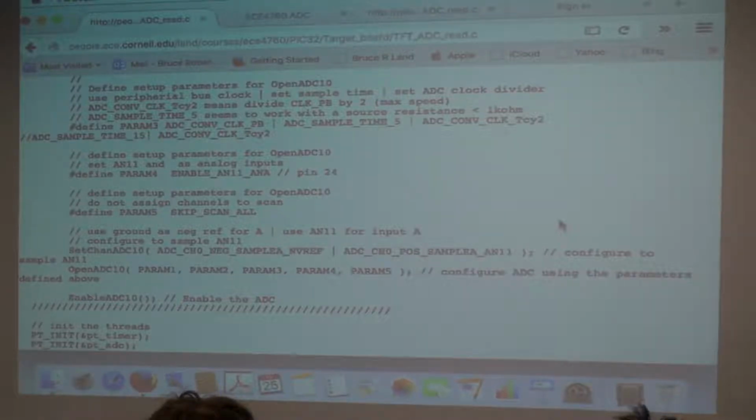And for controlling an analog control, you don't really care if it's off by a few percent, because you're going to compensate visually for that anyway, and it won't be off more than 1 bit even if it isn't self-calibrated. There will be a little zero offset, however. There's a few millivolts of zero offset, which again you don't care about for the control example that we're doing. So that I haven't played with.